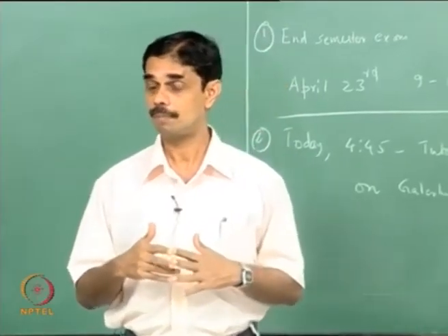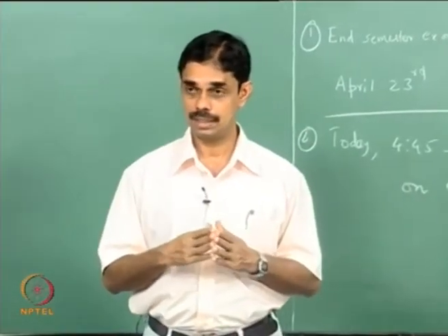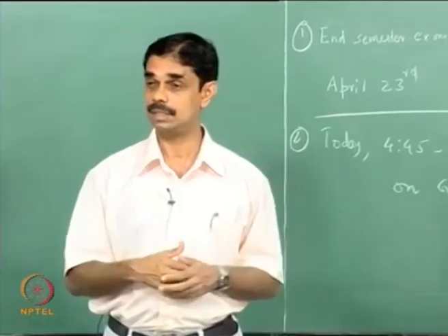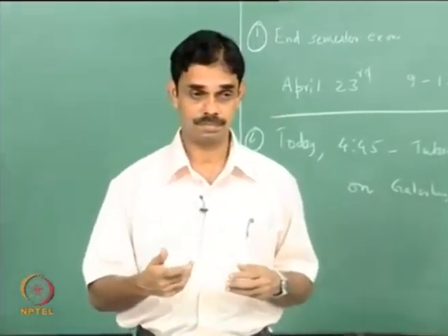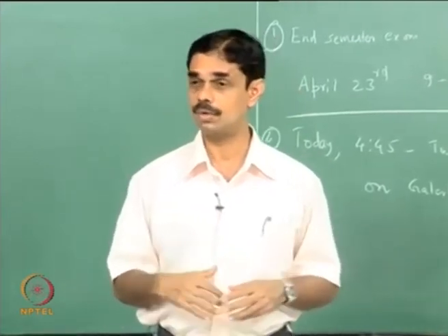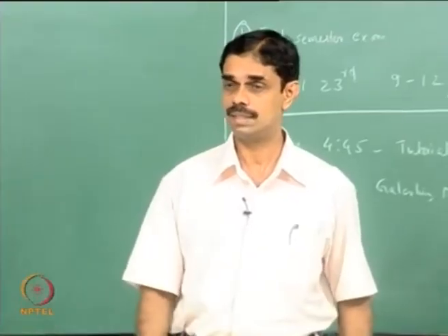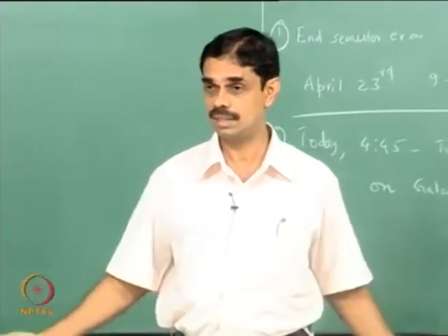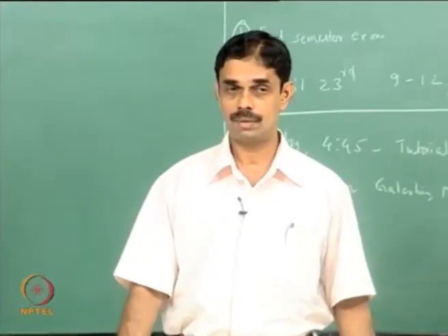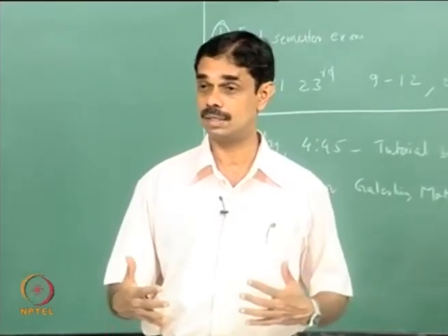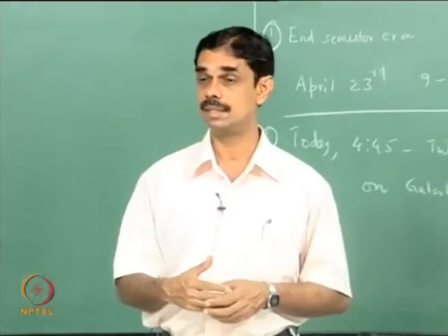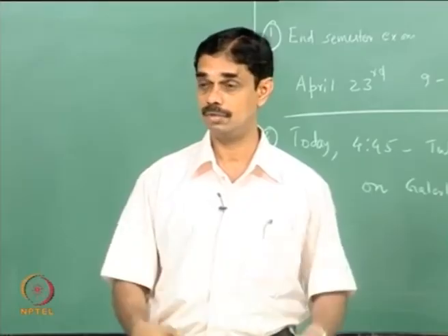You can do the same premixed flame analysis with equivalence ratio fluctuations and see what happens to wrinkles and so on, and there are many papers in the literature which work that out, particularly by the groups of Santavicca from Pennsylvania State University and also Lieuwen from Georgia Tech. I would not look at that because it is in some sense a similar kind of analysis, with the same machinery you have to work out. But I want to introduce the fuel flow modulation and airflow modulation that happens in a more practical combustor, which results in equivalence ratio fluctuations, and then we look at the consequences.